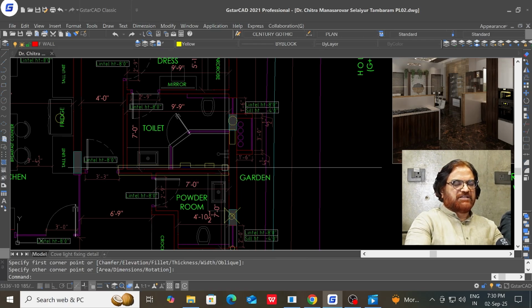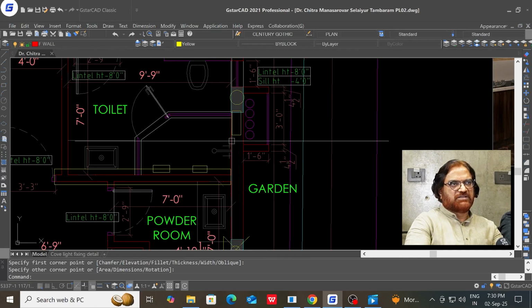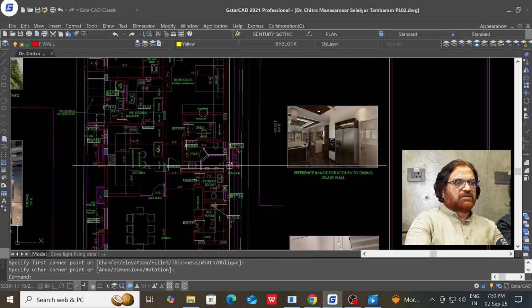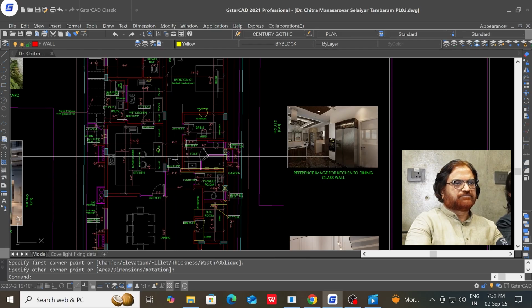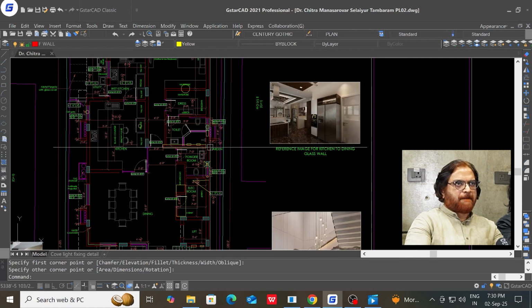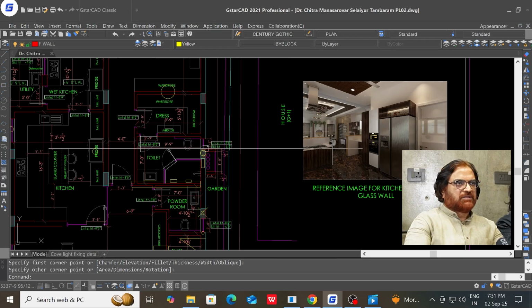So this is better at 9 inches, and I would like to see this column moved a little bit down without obstructing the body shower areas. So a little bit of fine tuning has to be done in this toilet to that extent. This setback compound also will be made into 6 inches to give more space. Otherwise entry is not possible. One step is required. Yeah, he can do that.